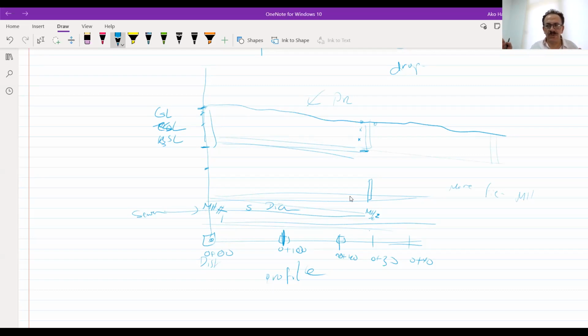When it is more than 2 A4s, it becomes difficult to read the data and it is confusing. So my suggestion when you design this kind of manholes is not to include more than 3 to 4 manholes in one profile.